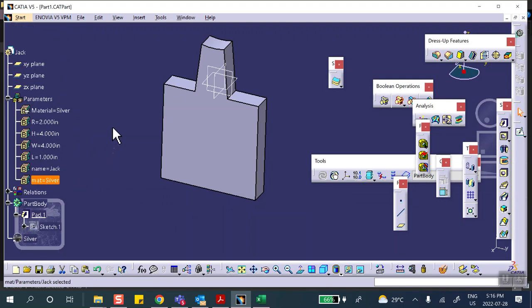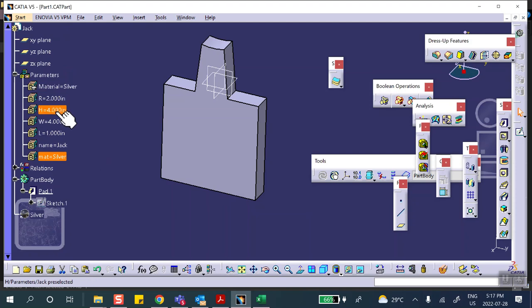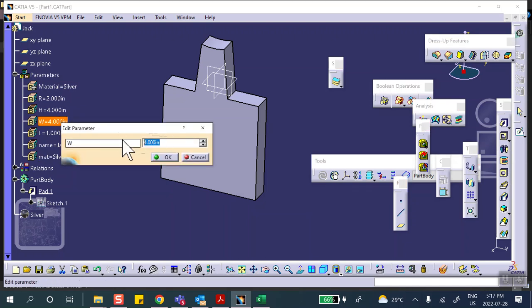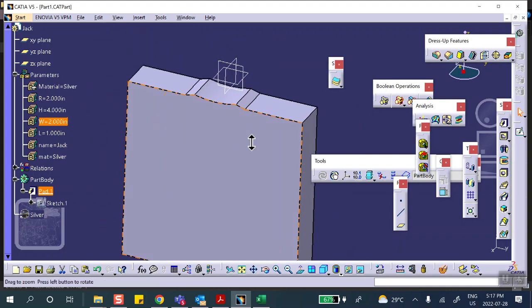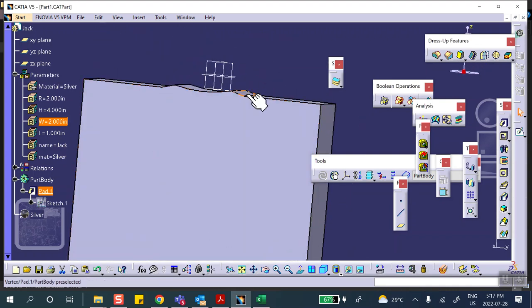Now, let me repeat. If you put unreasonable numbers so that it screws up your sketch, from that point on, if you try to change it back to where that number was, you might have a problem. So this is why I actually undid all the stuff, went to a configuration that I liked, and then started changing from that point on. So let me see here. What happens if I put a 2 there? Right. You see, it is exactly what I asked it to do.